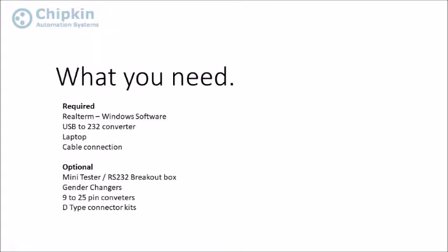This is what you'll need. I use RealTerm. I used to use HyperTerminal, and I never came to love PuTTY, but I hear it's great, so feel free to use what you like. I need a USB to 232 converter, a laptop, and a cable to connect to the device that is transmitting data.